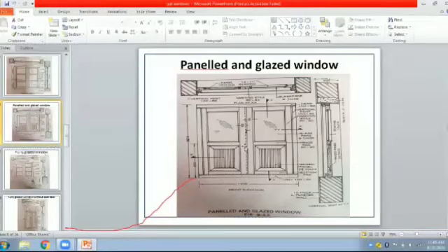Now, if we cut here, then this shows the maximum components of this window. When we cut it here, in the sectional plan, we draw the section of this vertical post, then this meeting style, hanging style, then this panel, and then this meeting style, and then this glass, and then hanging style, and then this vertical post.